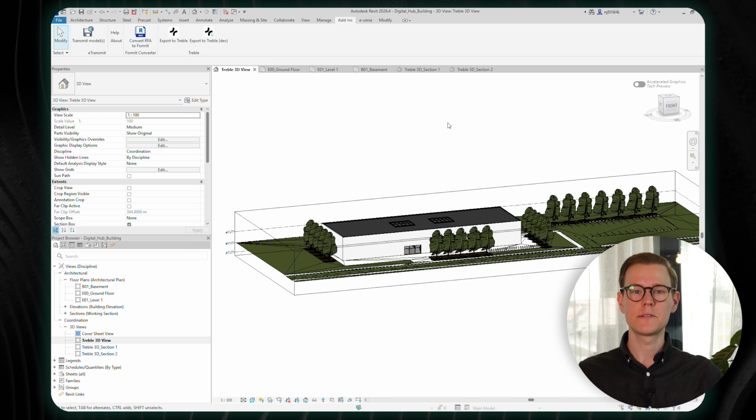The next plugin that we've released recently was for Revit, and this is great for our BIM users. Instead of needing to create a secondary acoustic model separately in a CAD tool, you can create your Revit model and send geometry straight into Treble. The Treble plugin for Revit is a little bit different as opposed to our SketchUp and Rhino plugins, because it also applies an automatic geometry simplification and space detection process.